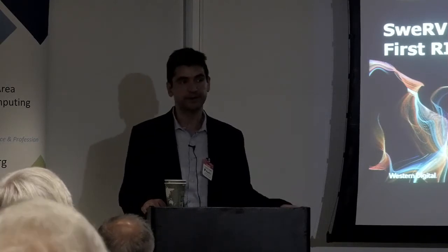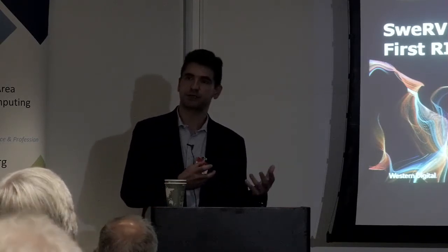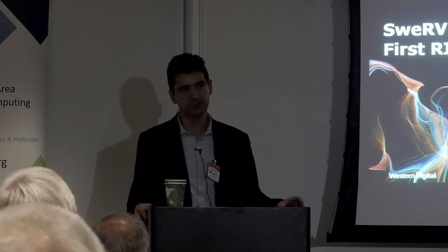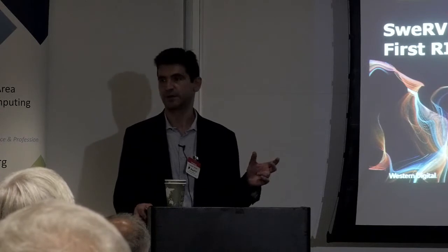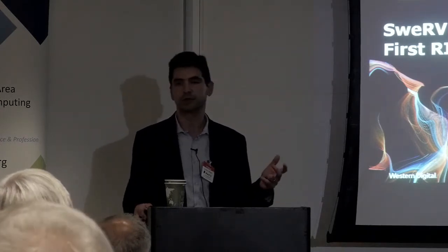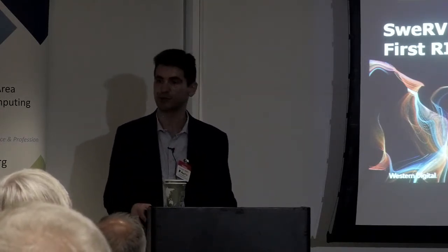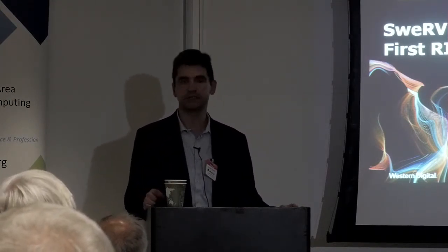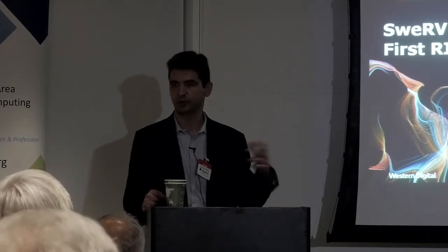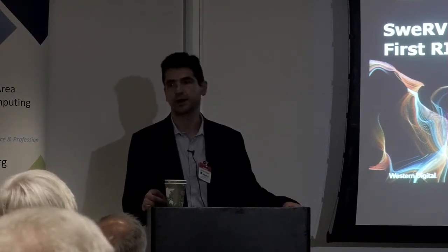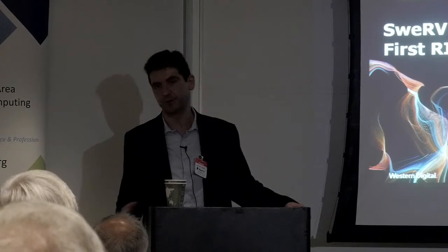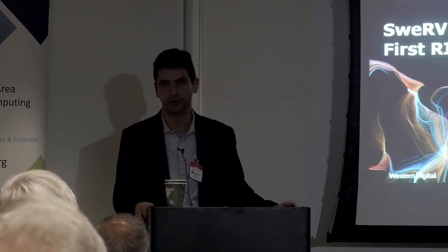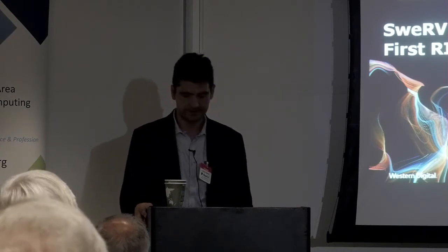And on top of that, since from inception this was envisioned as a kind of future computer standard, there's a part of the instruction encoding space that's reserved for proprietary instructions. So if your company wants to have some secret sauce, there's a part of the code space that they can use specifically for this. They have a guarantee from the standard they're not going to collide with future compilers. But then they have to build their own compiler extensions or do assembly inlining or figure out how they're actually going to use those features.